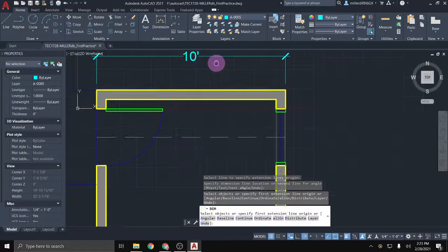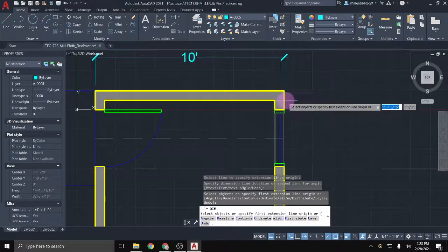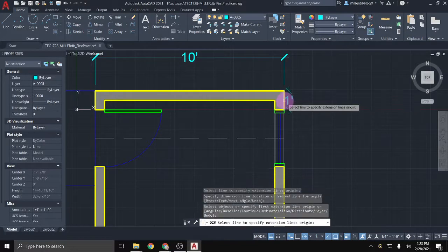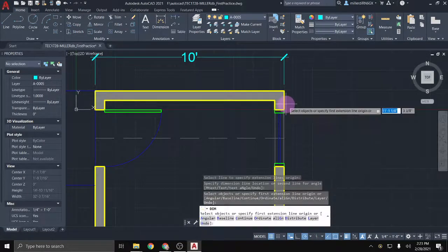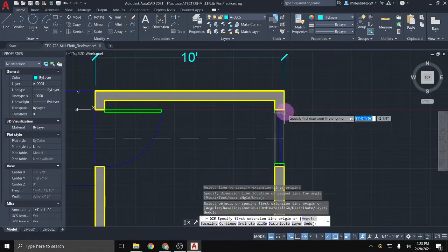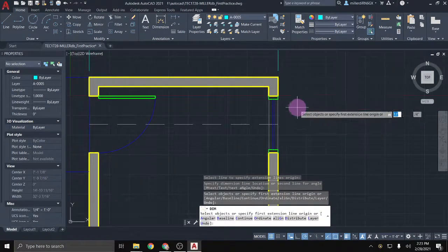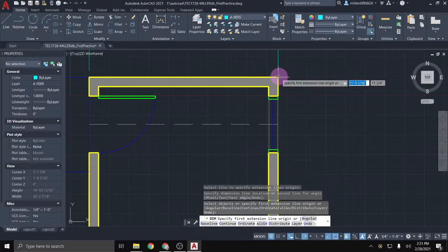One of the issues that students tend to have with quick dimension is when it comes to things for windows and stuff, because it doesn't know to do automatically to the middle of that window. So it's doing all of these weird little measurements and things, which is why then you can click to a center.